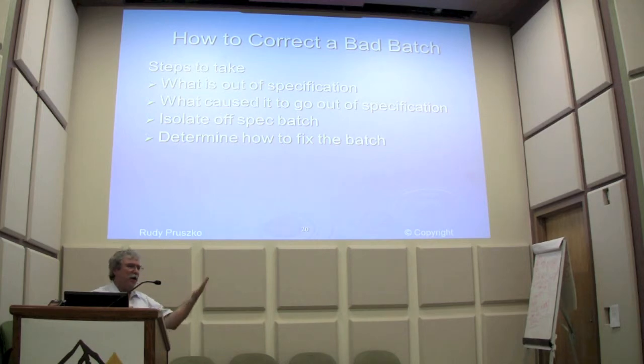And if you look at it, when I say look at the water content going in, you may say to me, oh, well, my feedstock coming in is only 0.5% moisture. I'm well within the limits. But then you're adding methoxide that you made, methanol, and you added potassium hydroxide. That creates about 0.3% moisture. So you're adding it with that.